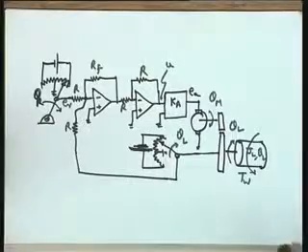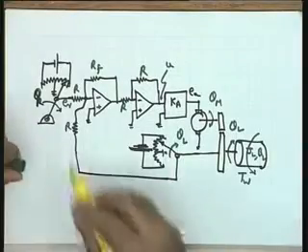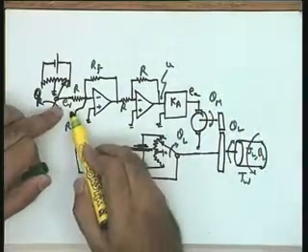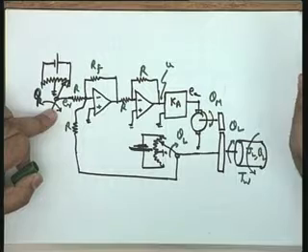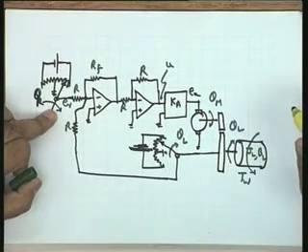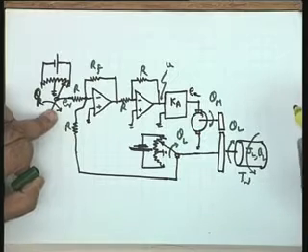Fine. One more diagram I wanted to take, and that is a position control system. Once you have got the speed control system very clearly, there will not be any problem here, it will follow very easily. See the objective of this system, and how does it work. In this particular case again, I have a reference input ER in terms of voltage, and this reference input is the commanded position. I want to command the position of the load, it is a position control system now, in contrast to the earlier system which was a speed control system.